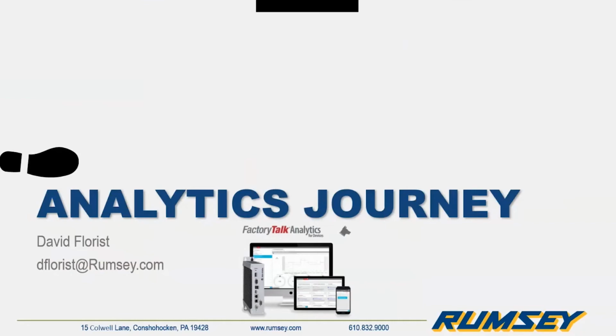Another scenario that I have is something I'm working on right now. I'm currently working on a demo for a customer using FactoryTalk Analytics for devices with IO-Link. And I thought I had my demo set up correctly. I didn't see any errors on my PLC. I thought I was pretty much good to go. When I plugged in my analytics appliance, it notified me that I had one of my IO-Link channels configured incorrectly, and I was able to find that and diagnose it within a couple minutes.